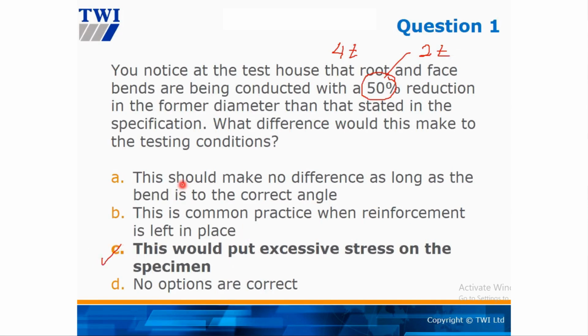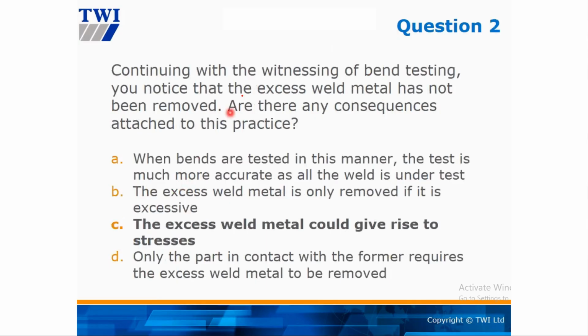Number 2, the same thing, but here they said excess weld metal was not removed. Again, because you've got excess weld metal, normally at the point of the toe, it will be giving the stress.